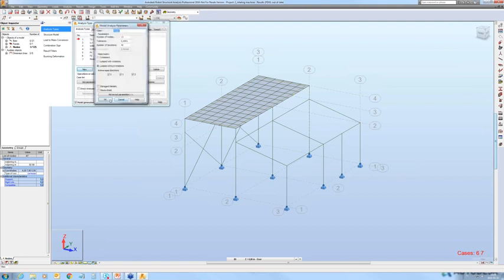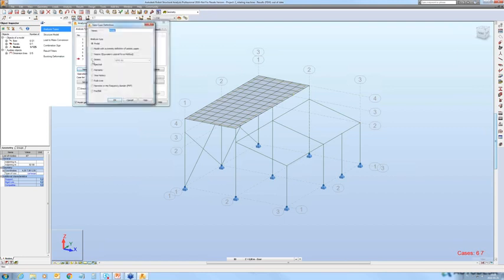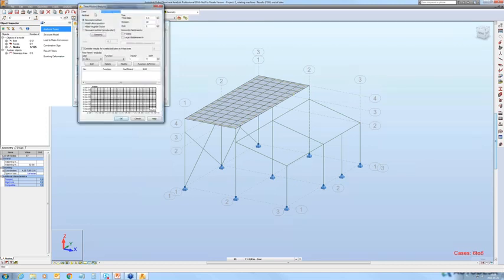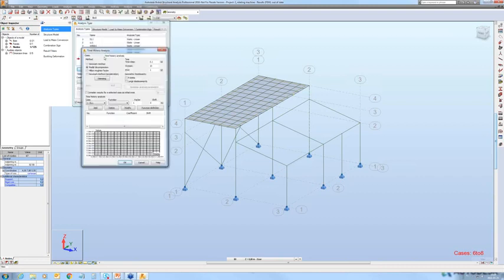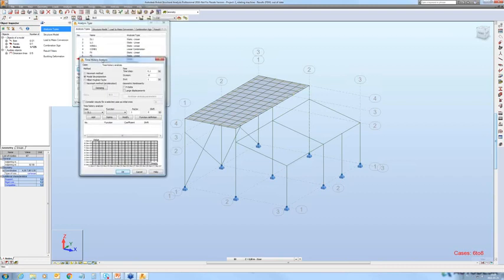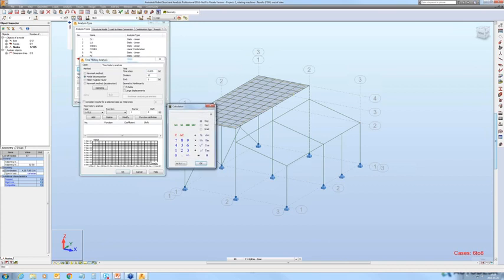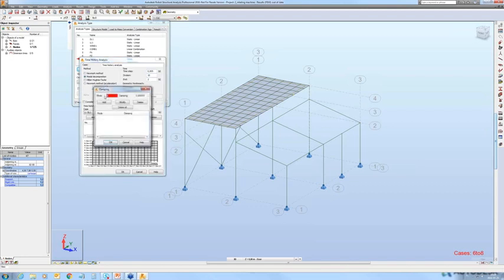First, I need to define a model case with default parameters. Then I can select time history analysis and, okay, modal decomposition method again. But we will have a smaller step this time, and end time that's going to be 2 seconds. Damping for mode 1 and all next modes will be 5%.